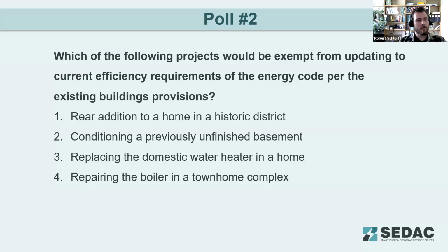While we're waiting for those answers, do you want to try to tackle the question about fire damage to a building there? So the definition of a repair is the reconstruction or renewal of any part of an existing building for the purpose of its maintenance or to correct damage. Generally, in the case of a fire, the assemblies are being rebuilt to correct damage. So that would be considered a repair in that case.